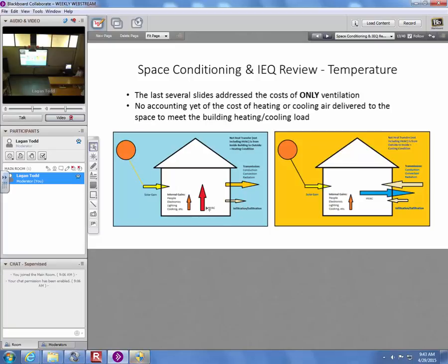And then we've got our HVAC system trying to add heat to the space to maintain this temp. And we've got the internal gains of appliances and people and pets and things like that. Okay, but in net we need all the energy coming in to add up to equal the energy going out if we're going to maintain a constant temp in here.